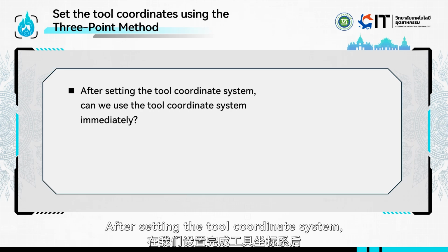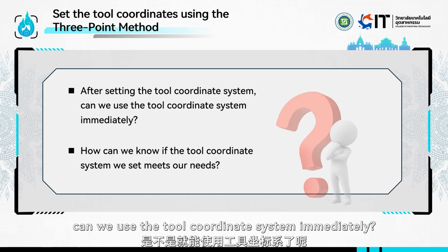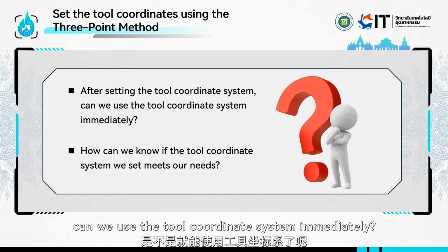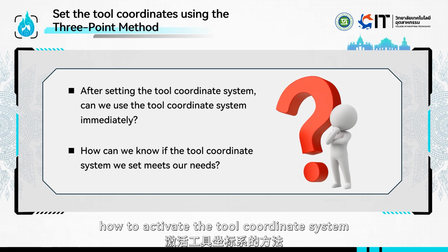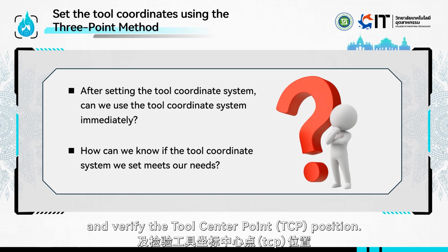After setting the tool coordinate system, can we use the tool coordinate system immediately? How can we know if the tool coordinate system we set meets our needs? Next, we will explain how to activate the tool coordinate system and verify the tool center point, TCP, position.